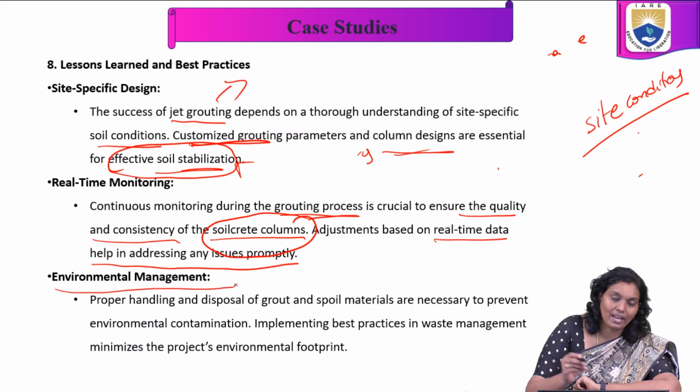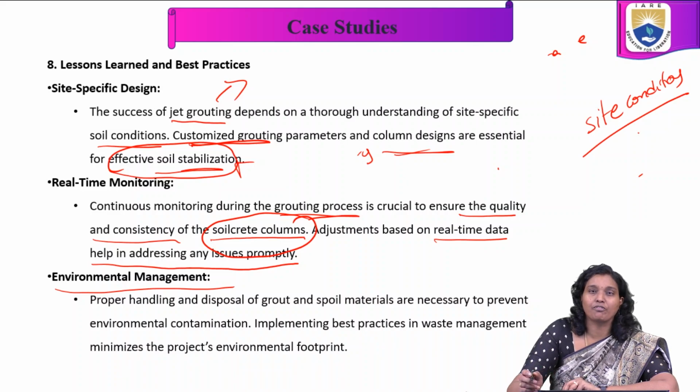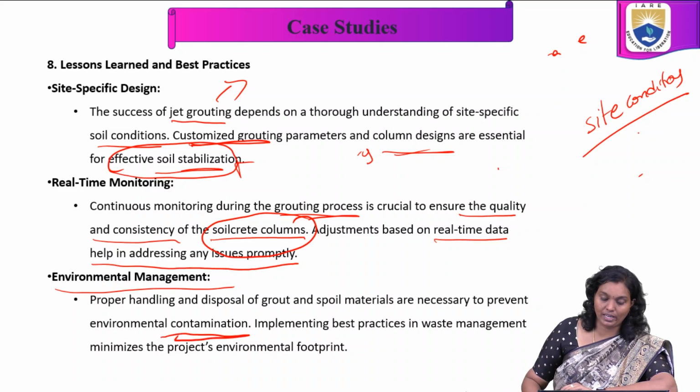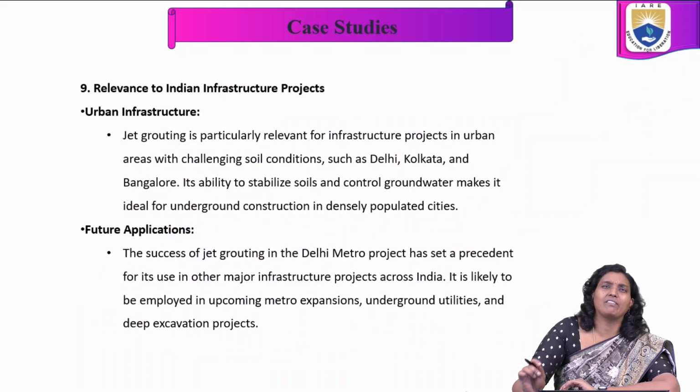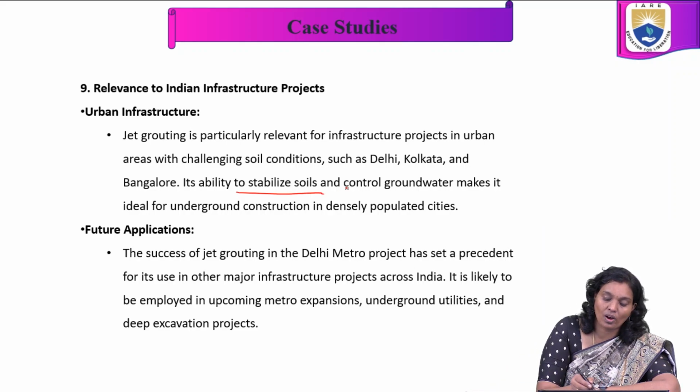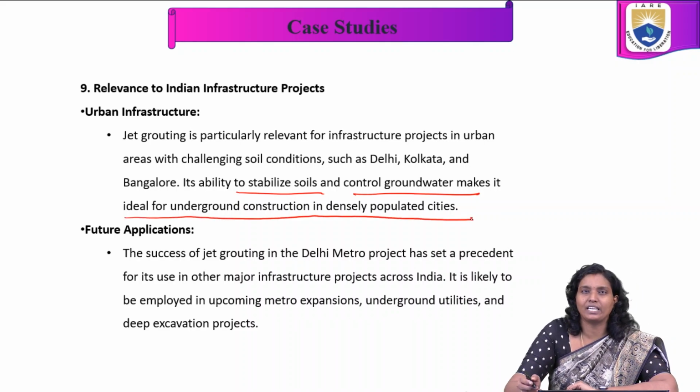In environmental management, proper handling and disposal of grout and spoil materials are necessary to prevent environmental contamination. Implementing best practices in waste management minimizes the project's environmental footprint. Regarding relevance to Indian infrastructure projects, in urban infrastructure jet grouting is particularly relevant for projects in urban areas with challenging soil conditions such as Delhi, Kolkata and Bangalore. Its ability to stabilize the soils and control groundwater makes it ideal for underground construction in densely populated cities.